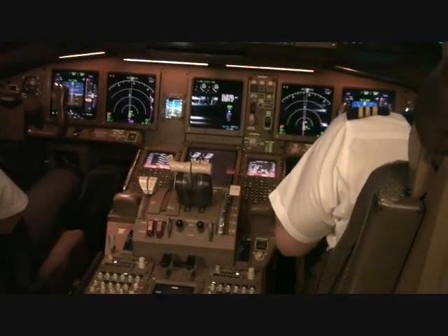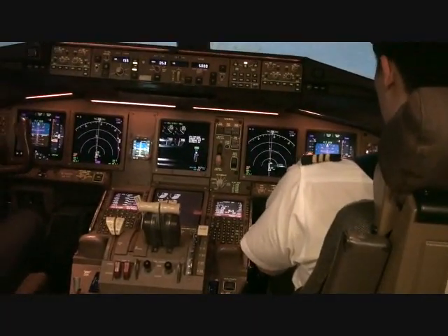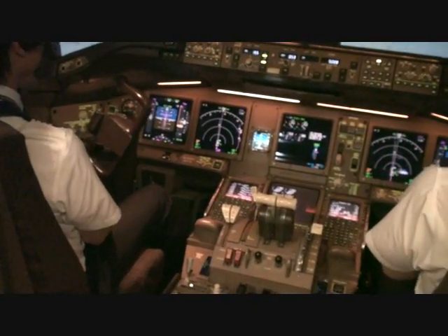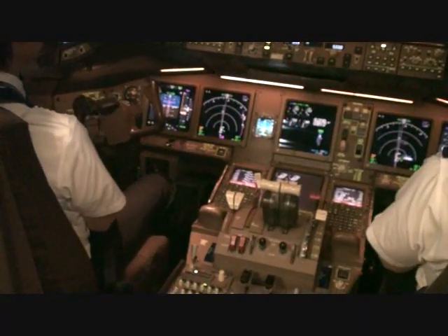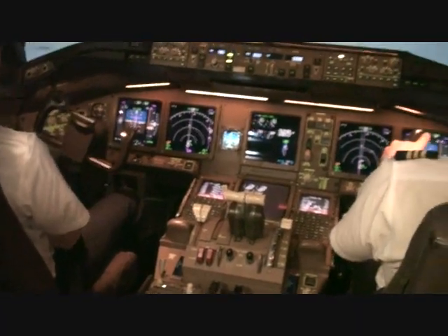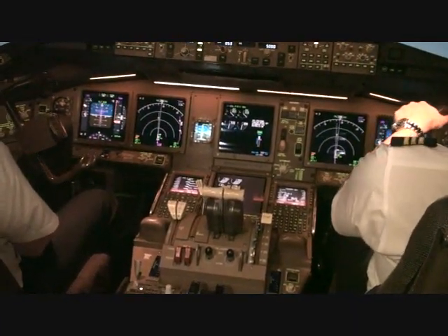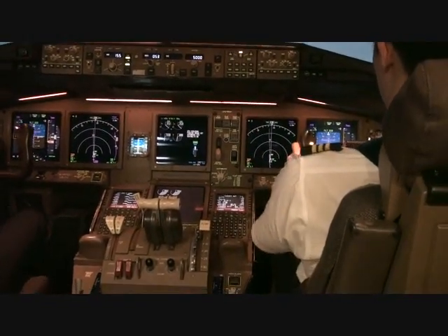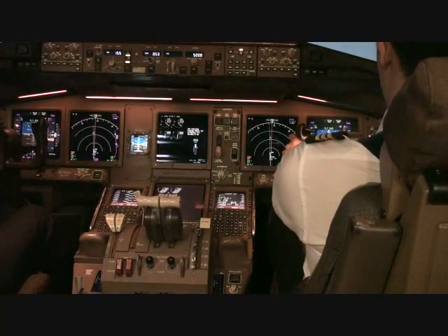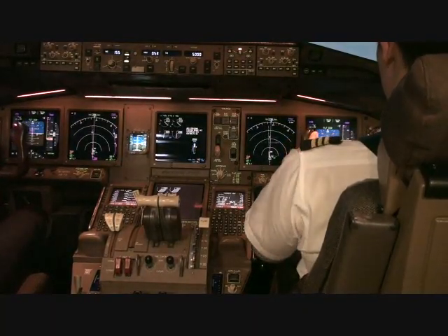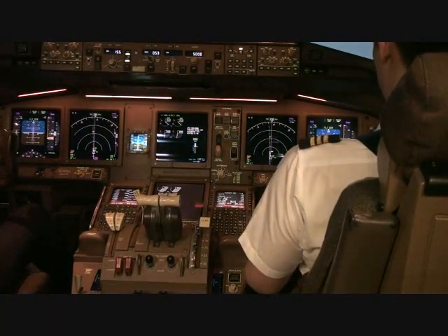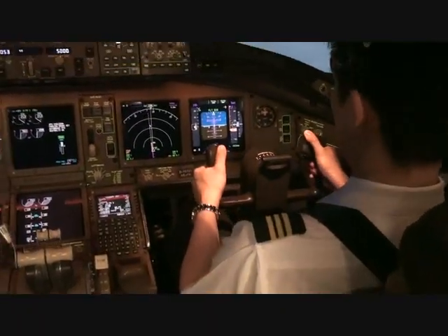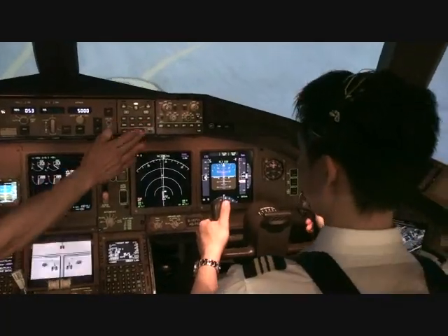Flight controls check. Make slow and deliberate inputs one direction at a time. To avoid nuisance flight controls faults, a complete cycle of the control wheel during the flight control check should be done slowly, more than approximately 6 seconds, and not combined with the check of the pitch controls. CM2 moves the control wheel and the control column to full travel in all directions and verifies freedom of movement and that the controls return to center.